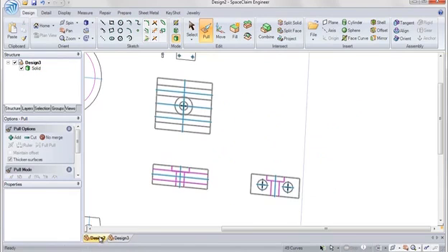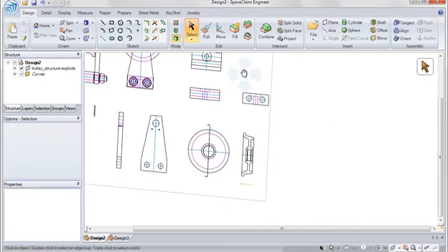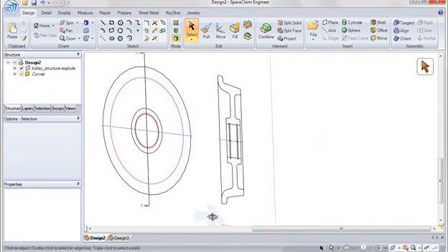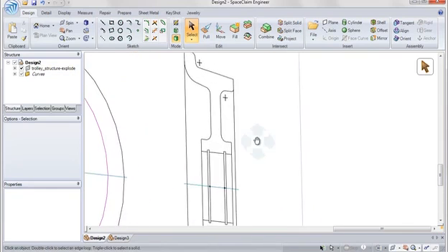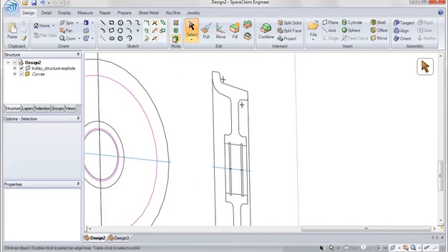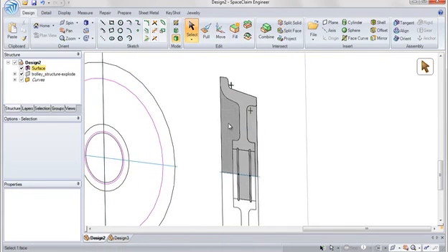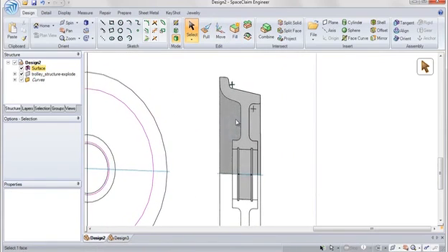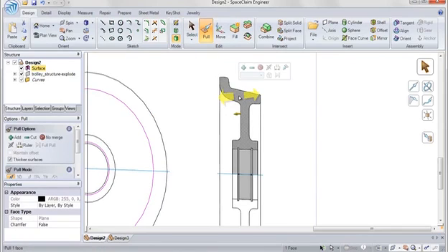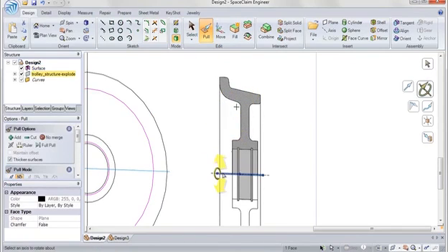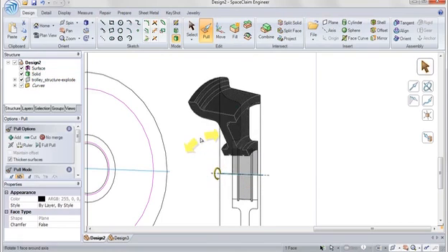Now back to this 2D print that I have, we also have a revolved part for this pulley. I can do the same sort of operations very easily making a revolve feature. So on the 2D print I can select what I want, click the fill command, it'll automatically fill in all of those bounded areas with surfaces. I can get rid of the ones that I don't want, and now use my pull command to pull the face that I do want, alt selecting a center reference, and hitting enter to create a revolve feature.